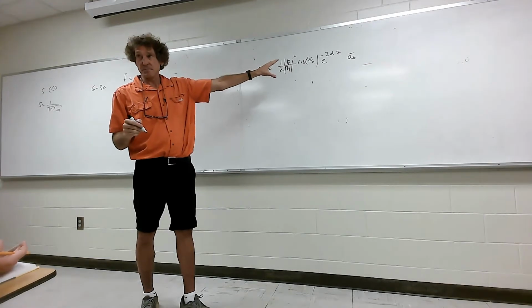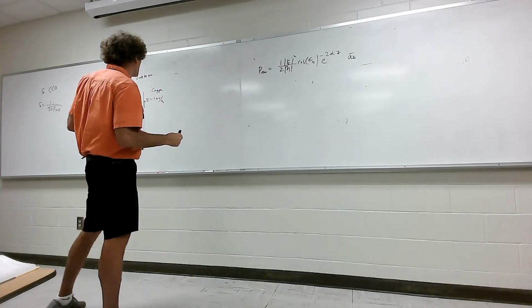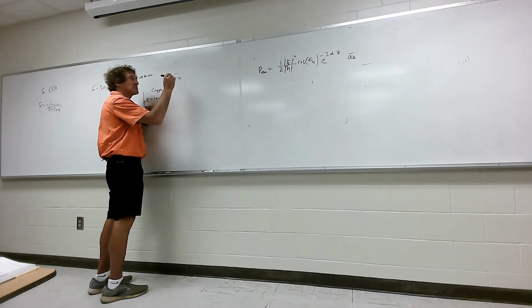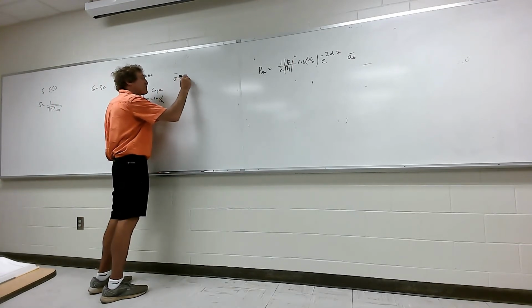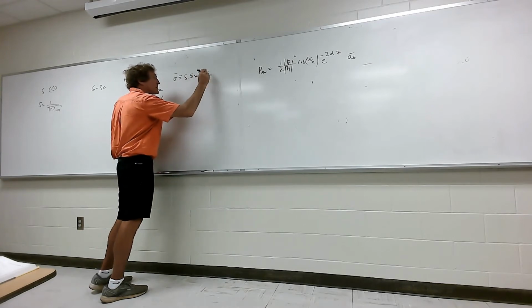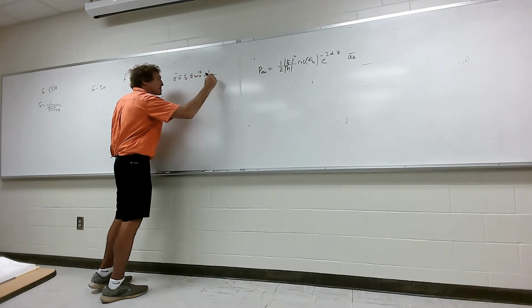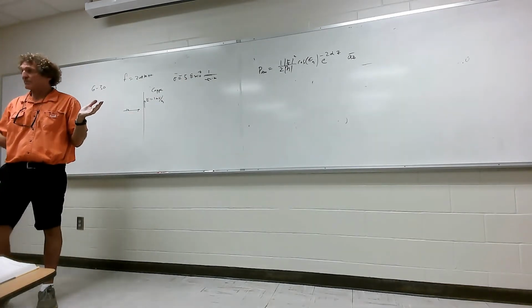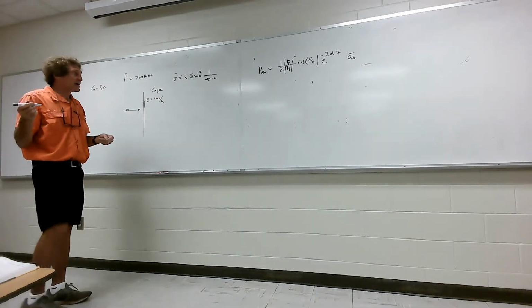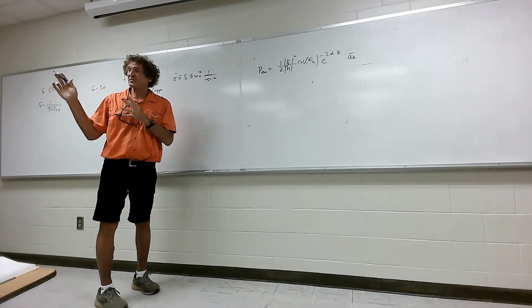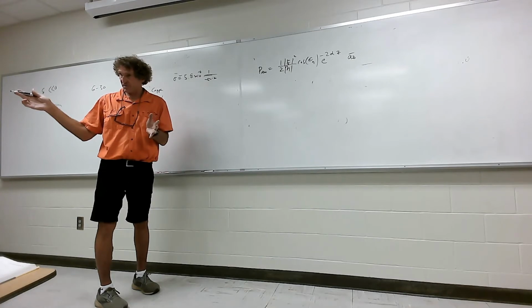That's the equation. Now, copper has a conductivity, in the back of the book, of about 5.8 times 10 to the 7th siemens per meter. That's huge. It's an extremely good conductor at room temperature. So we're going to ignore the omega epsilon term for the impedance.